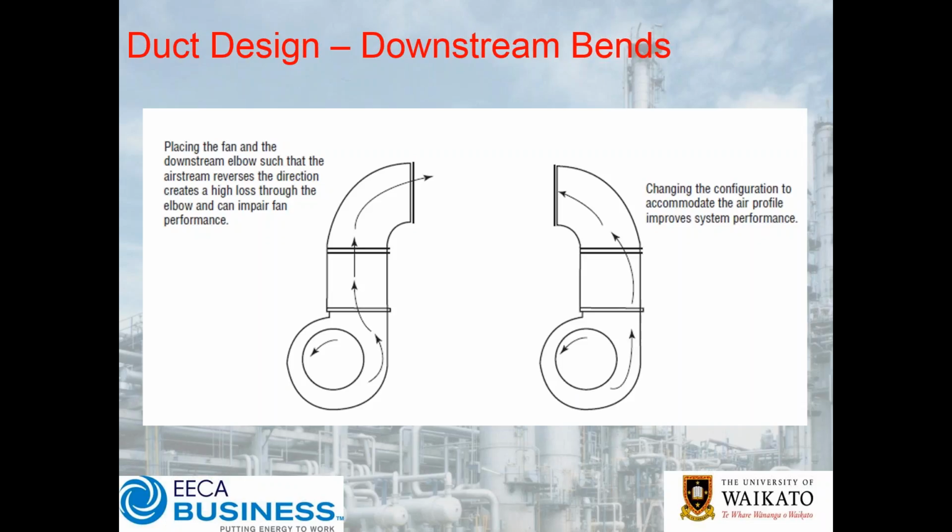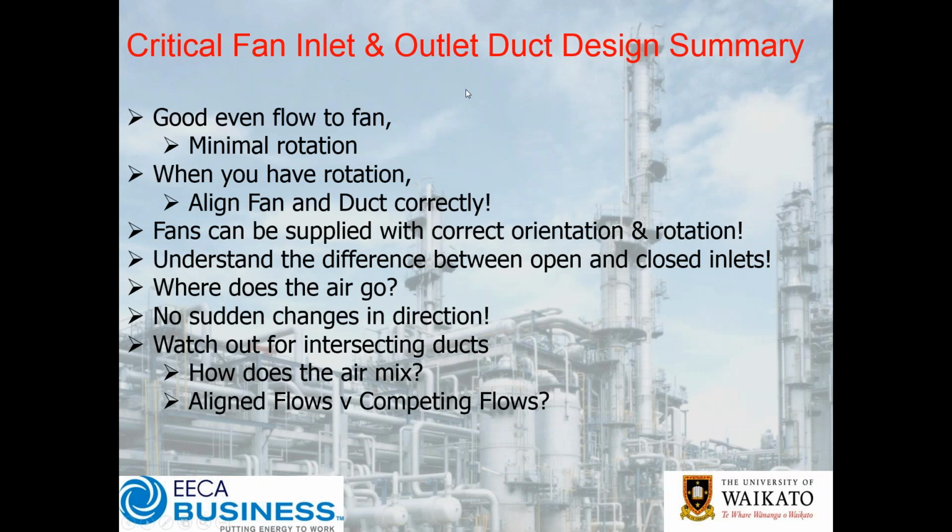The other thing you could do is look at just reconfiguring the fan housing and so on. And obviously the other thing too to bear in mind is it's not unreasonable for that whole fan to be actually rotated 90 degrees, and it could be feeding straight out on its side as opposed to vertically up, vertically down. And you can actually almost specify, if you're using a reputable fan supplier, any angle for that outlet of the fan in the housing within reason. Obviously if you want a very particular angle you might have to pay a little premium for it, but all these sorts of things are quite easily done at the design stage.